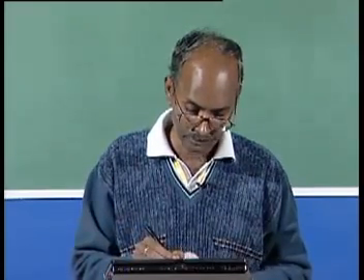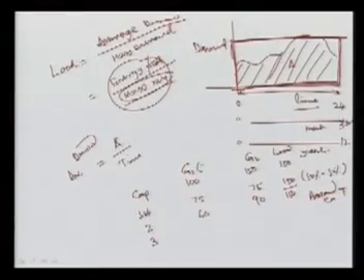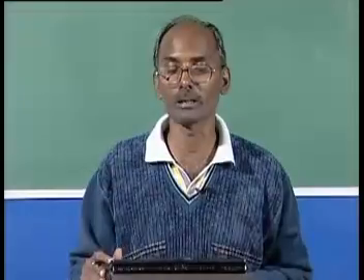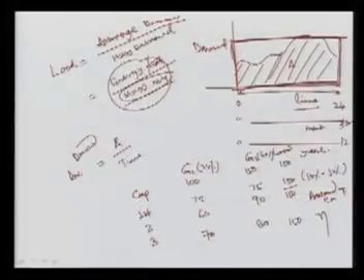Another case: let us suppose the efficiency of this is 35% and the efficiency of this power plant is 40%. So we can load according to the efficiency. Again our objective is to meet the load demand of 150, and if we go by efficiency, we load 70 here and 80 here, and again we are meeting the load. The more efficient plant takes more loading, the less efficient takes less. Various other combinations are now possible, here I can say 71, why not 79, and so on and so forth.